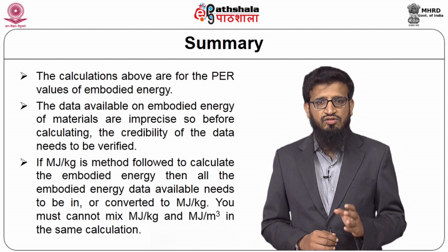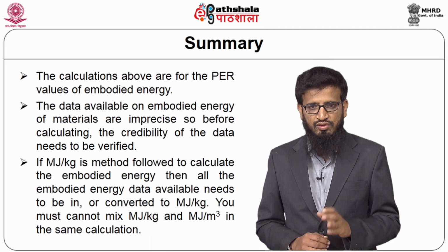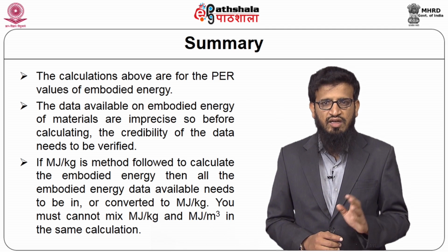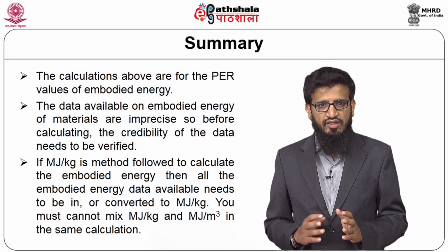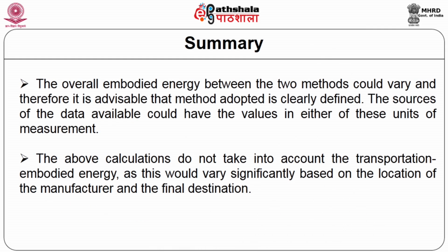You cannot mix megajoules per kg and megajoules per meter cube in the same calculation, because that will take your result in a different direction. The overall embodied energy between the two methods could vary, and therefore it is advisable that the method adopted is clearly defined. So whenever you are doing your exercises, please mention which method you have adopted to do the calculations. The above calculations do not take into account the transport.